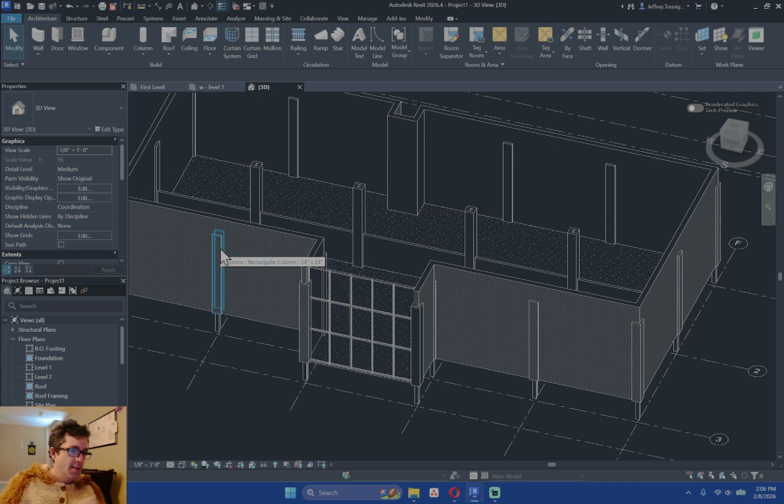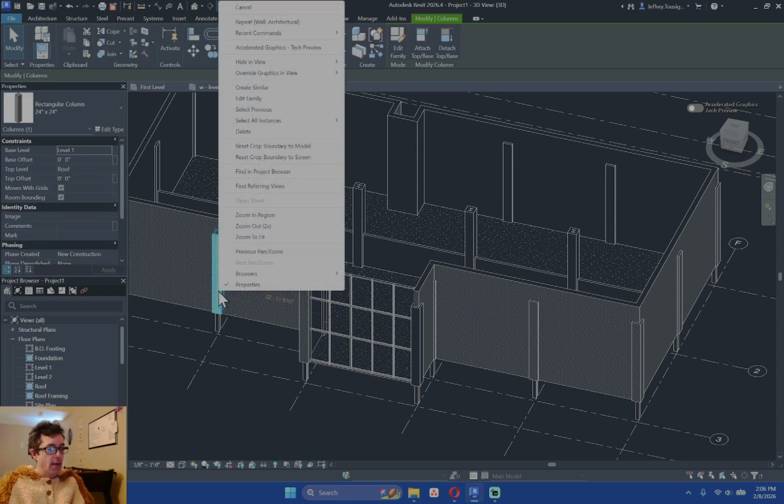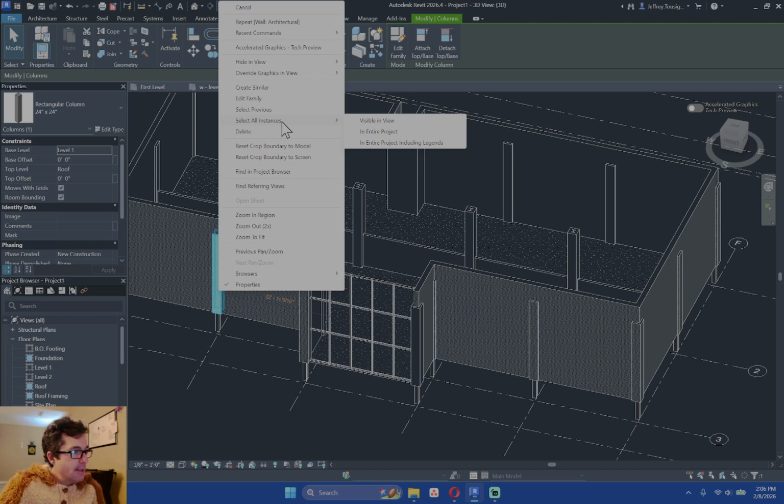I'm thinking these exterior columns need to go to parapet too, because graphically, if they are going to jog out like that and create a pilaster looking view, we would probably want those to go up. Yeah, and I'm not going to make them go down because the architectural columns in Revit aren't actually carrying data. So we wouldn't need to graphically show brick going underground to take advantage of any of Revit's tools.